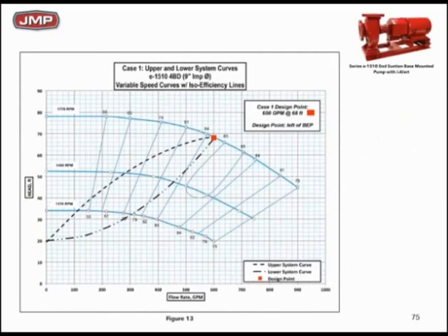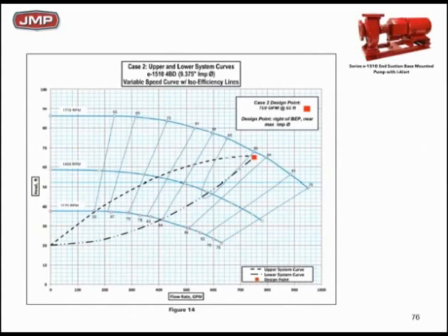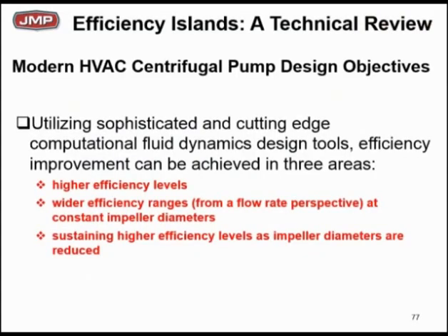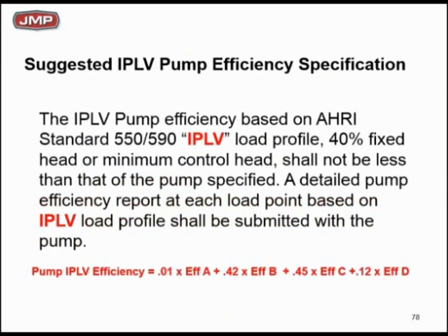We would not argue with you at all that it might be slightly higher if you do a good pump head loss calculation. If you don't, you may fall off the pump curve. You don't have much safety. You're losing your safety factors. So in a modern pump design, we're able to control these areas a little bit. We're making them bigger. And I want to get back to this load profile and bring this together for you, where we want to go.